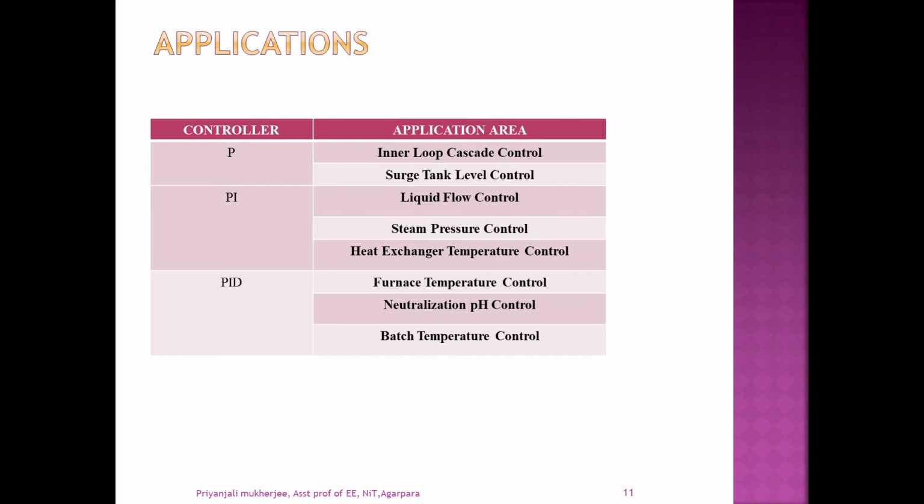While the dynamics of pH are challenging from a control perspective, they are well suited for PID controllers. Specifically, the dynamics of pH tend to be slow as the amount of acid that's typically added to a process is relatively small when compared to the volume of existing liquid. The slower dynamics allow the derivative to improve the control without overworking the final control element.